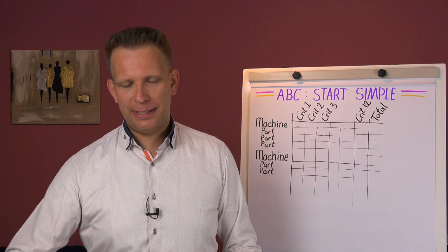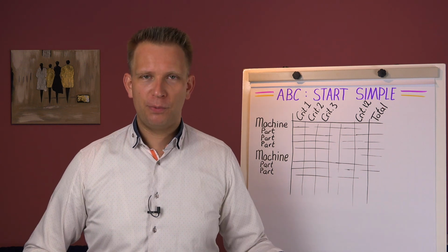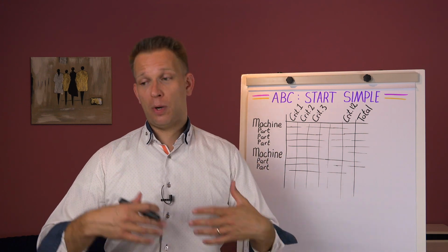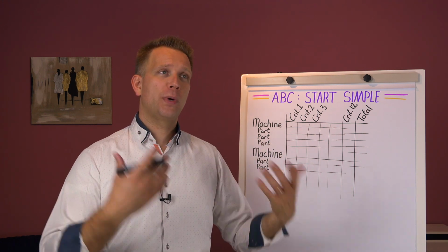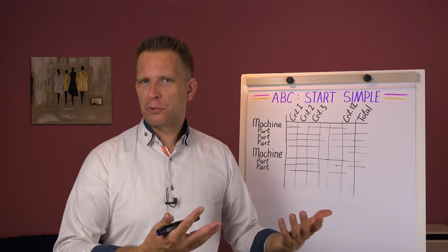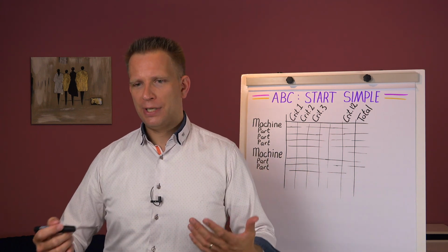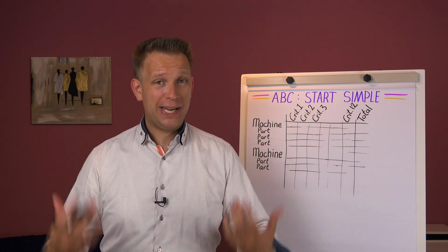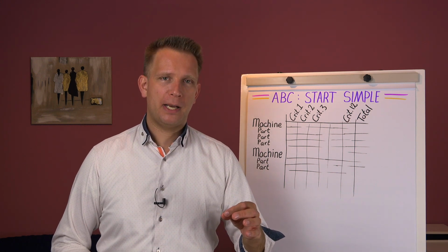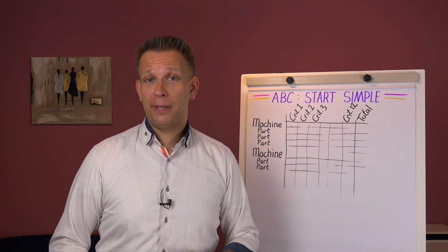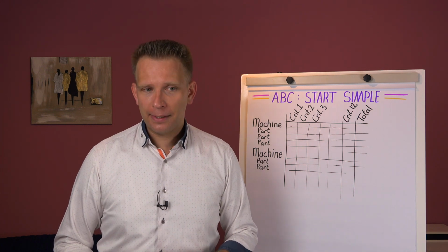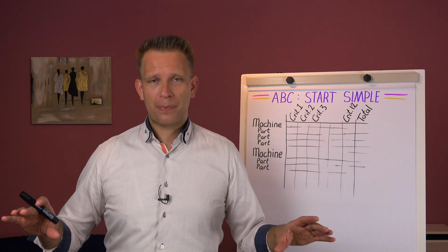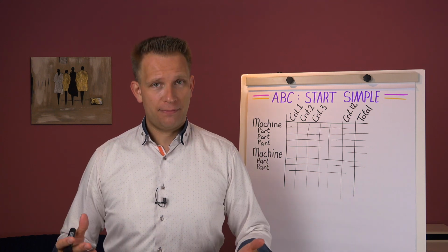Whether you use it as a TPM pillar or a general continuous improvement concept, when we are looking at what machines require very active plant maintenance, where do we need to keep more spare parts on stock, which machines require the best sort of contracts to service them, or very good in-house teams who can always get them back up and running, or increase the reliability so much that that isn't even really needed. We understand that you don't want to do this with all of your machines because that is very expensive.